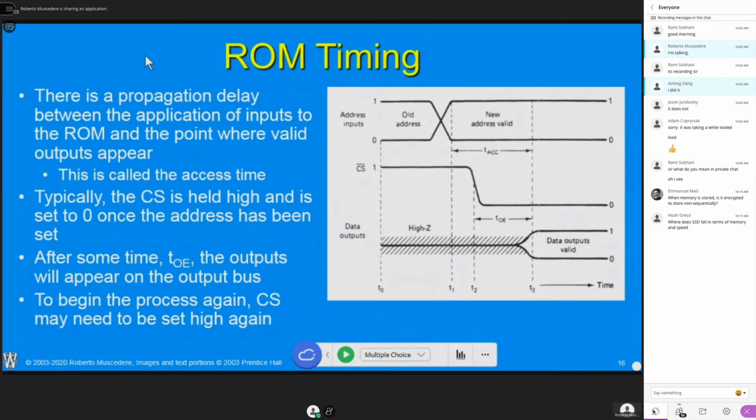When we started out building electronics, we were always faced with the problem of how do we make things functional and also make things cost effective? Now we have better ways of doing this stuff, better ways of interacting with these memories. But the one thing you'll notice with legacy memories is there's no clock to them. And that makes interfacing with it a little bit more challenging. So we have to look at these timing diagrams.